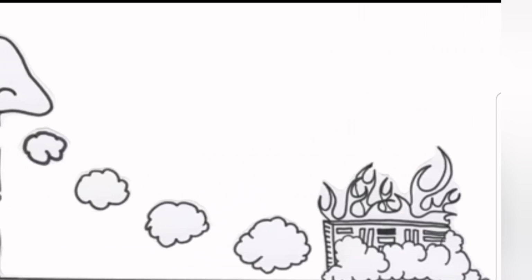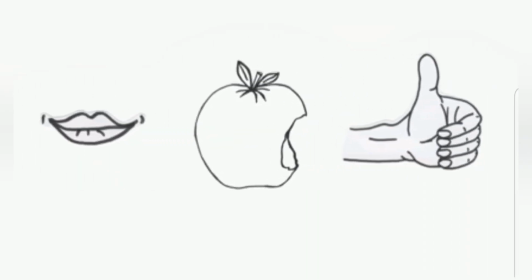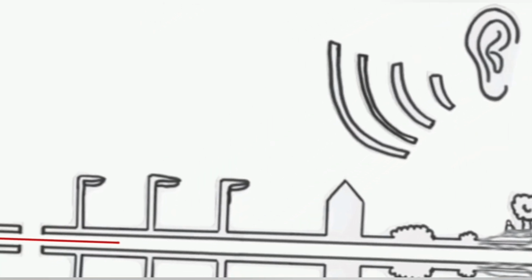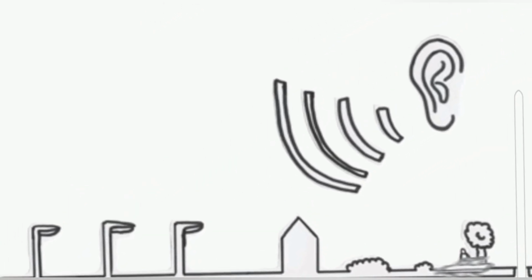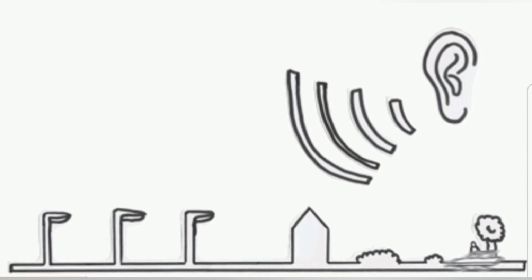A resistance temperature detector, or RTD, is a passive sensor. It is a device whose resistance will change with a change in temperature. To take advantage of this change in resistance, an external supply or an excitation circuit is required to produce a change in voltage. Another example of a passive sensor is a strain gauge.